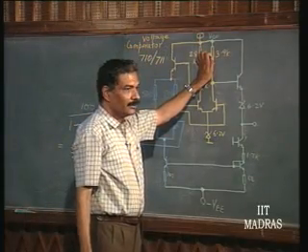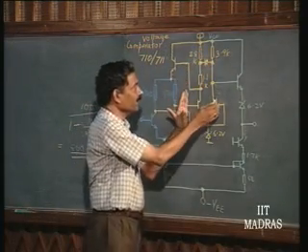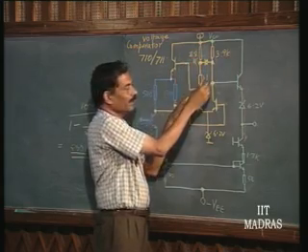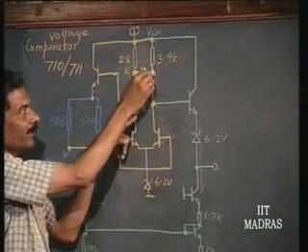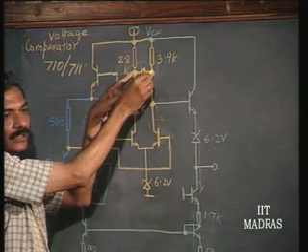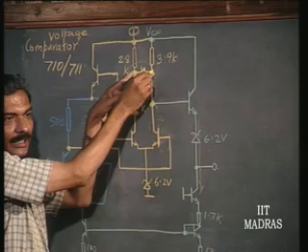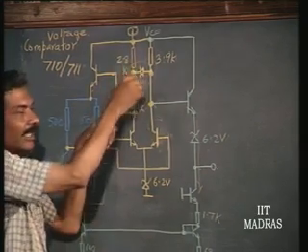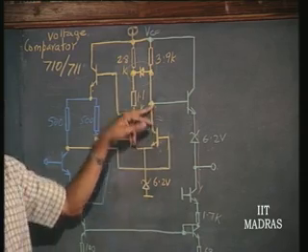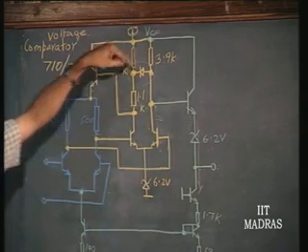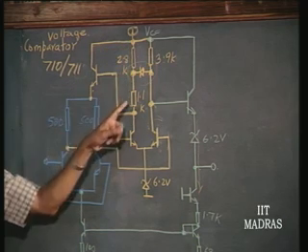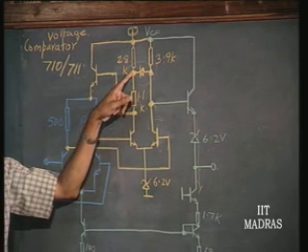This diode is not going to conduct if this is going to be in the active region, you can see, because these are identical stages, 1.1 k plus 2.8 is 3.9. So, the voltage between this and this is going to be 0. Therefore, this is going to be reverse bias most of the time, okay, when it is in the active region. So, this diode is not in picture, but the moment this goes off and this is pulled up to VCC, this potential is rising very fast up to VCC, and it is clamped down to a certain DC potential which is less than VCC.